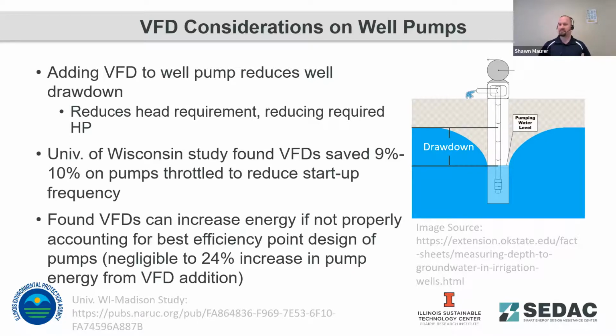And so in some instances, particularly where your system curve is slightly to the left of the best efficiency point of your pump, usually most designs for consistent application tend to have that design where the system curve crosses just slightly to the left of the best efficiency point.